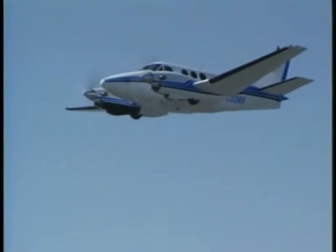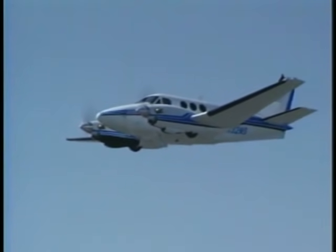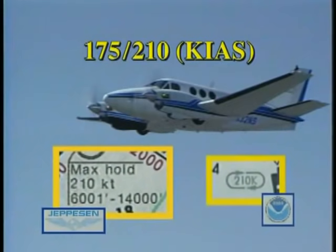With some exceptions, the holding speed for propeller and jet aircraft is 200 knots indicated airspeed, up to 6,000 feet MSL. Above 6,000 feet to 14,000 feet, the maximum holding speed is 230 knots. And above 14,000 feet, the maximum holding speed is 265 knots. In some cases, holding speed may be restricted to 175 knots or 210 knots indicated airspeed. When this is the case, you will see an icon or note on the chart depicting that holding speed.